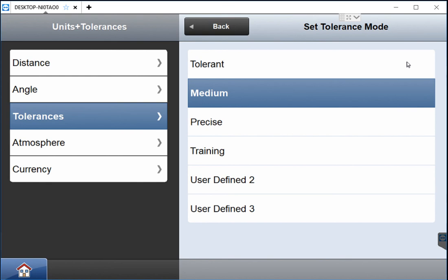The point you are selecting may have been incorrectly created, or the point you are measuring on the ground may be incorrect. An example of the last option would be bad control line intersections. The concrete layout team may have errors in their control lines which would cause the intersection to be out of alignment with the building. No matter how many times you measure it, you will not get the correct reading if this is the case. At that point, you would select another point to measure and let the concrete layout team know that they have a problem with their control.